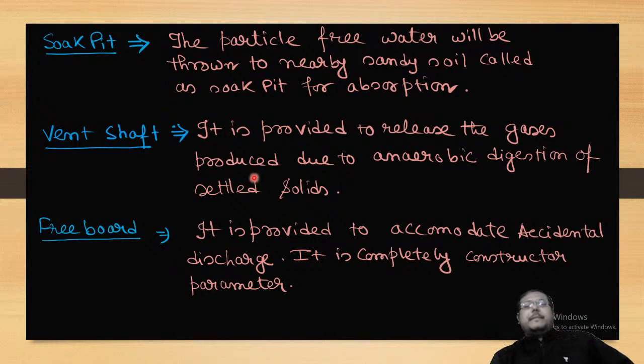Now, what is the job of the soak pit? The particle free water will be thrown to a nearby sandy soil called a soak pit for absorption. Vent shaft: it is provided to release the gases produced due to anaerobic digestion of settled solids.